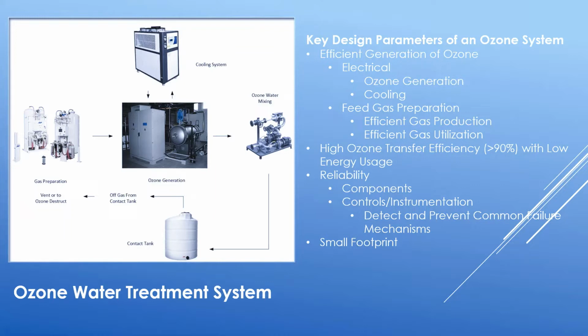So in other words, a person who works in an area 40 hours a week cannot be exposed to more than 1/10 of a part per million on average during that time. And most ozone systems will have instrumentation to shut the system down should those ozone levels be violated.